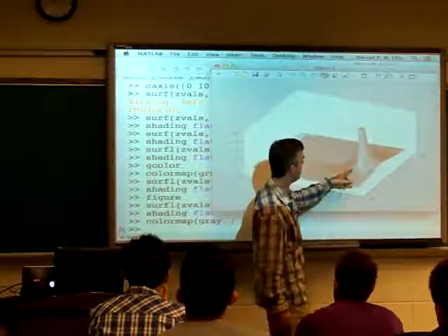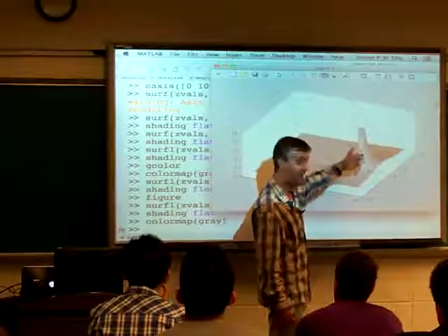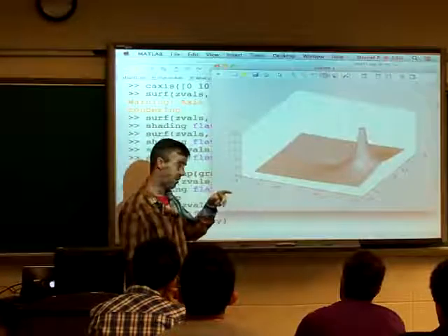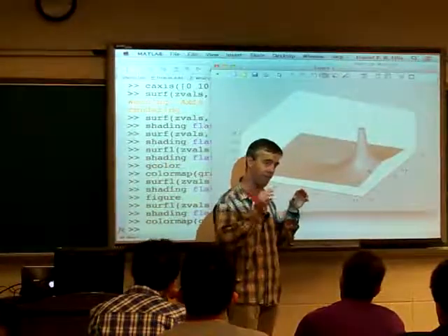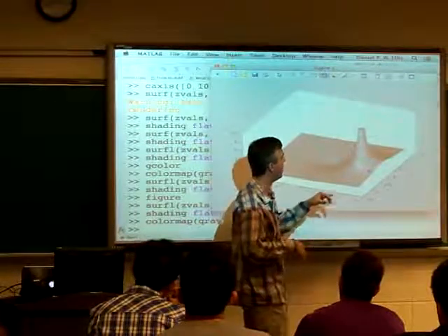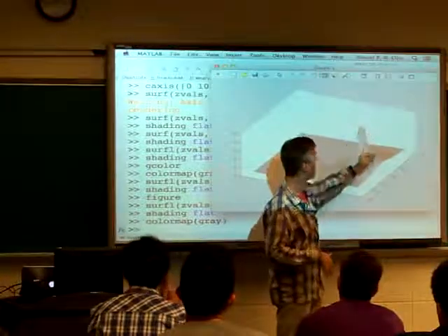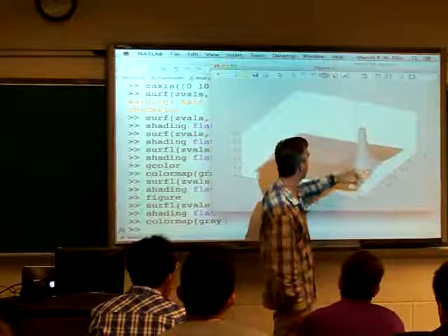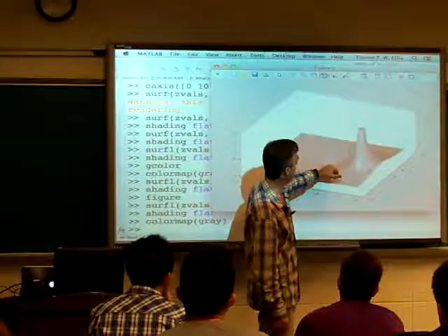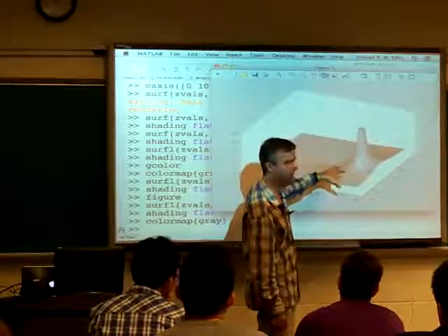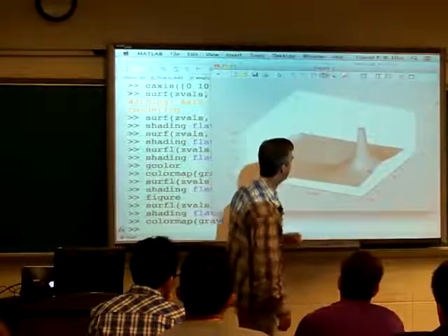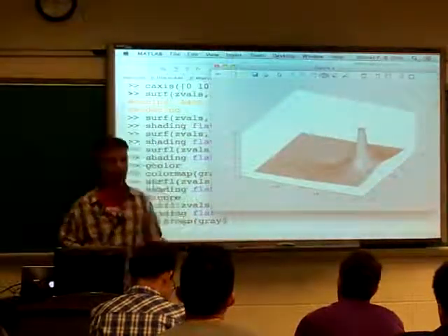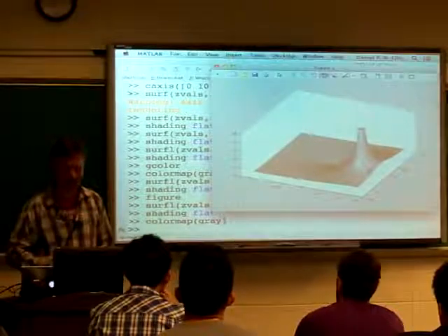And what we see here is this thing sticking up, which looks kind of like a tent with a tent pole in it. That's the pole, right? This expression, 1 over 1 minus lambda z to the minus 1, has the denominator going to 0 when z equals lambda. So this is a root of the denominator, so it's a pole where the magnitude of that closed form expression goes to infinity. There's a 0 here. It turns out that when z is 0, that whole thing goes to 0. So that's kind of a not very interesting 0, because the zeros at the origin at z equals 0 are not as interesting as the zeros elsewhere.